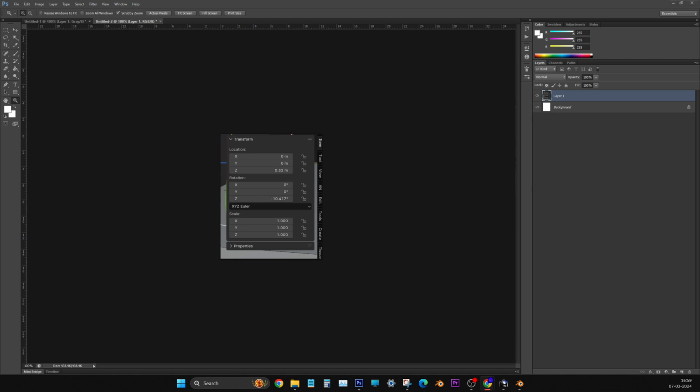Just select the cube again, back to the cube. Here, with that cube you have created a staircase. Now go to the object offset field. That field is there in the right side settings, that black color field. In that field you refer to the empty. Now select the empty.